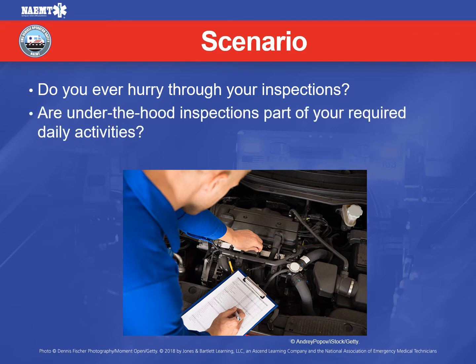Okay, are under the hood inspections part of your required daily activities? Absolutely. As you found out in this scenario, if they would have done a thorough pre-trip, he would have noticed that the fan belt had been cracked or broke or was about ready to come off the alternator. But because of that, the other crew that took the ambulance is now broke down and has a dead battery.